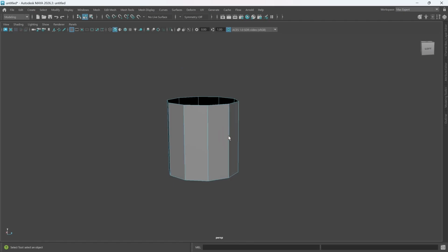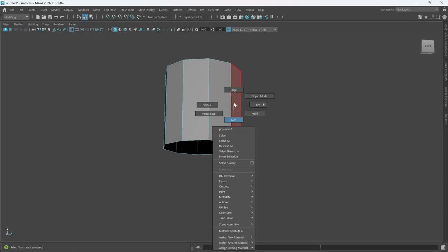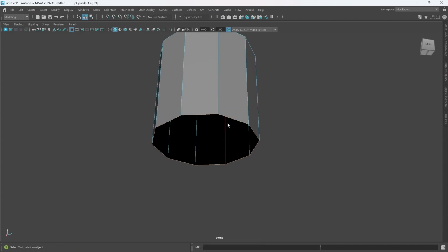The bottom part of our mug is a little bit rounded, but not that rounded, and it is also sharp. So we right click, go into the edge mode, double click on this edge to select the edge completely. Now, like I said earlier, we are going to be using some advanced techniques in Maya to model so that the modeling is going to go fast. Normally, when you select the edge and you want to extrude, you are going to hit Ctrl plus E to enable the extrusion. But you can also do Smart Extrude in Maya.